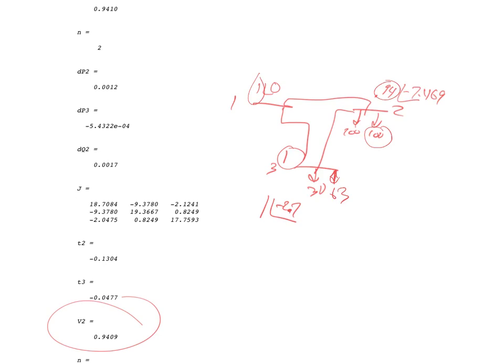So I have 63 in, 100. You can see here that with these magnitudes the same, this one's providing 36, this one's 36, and this one's 63. So you can't tell exactly if it's going to be shared because it's not exactly that case, but you can see that there's some sharing there. But more importantly, look at the magnitude here. 0.94 is much lower, so I'm getting 100 megavars. All the reactive power is going there.